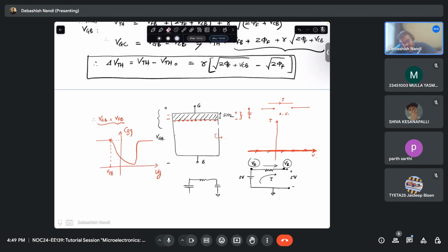Let's say you have some kind of source here. This is R, this is C. You apply a pulse, a current will flow, and at infinite time, what will happen? This is the step you are applying. How will the voltage across the capacitor be? Let's say VO will be something like this. So 5 volt will appear after some time, let's say 10 tau, where tau is equal to RC. It may not be exactly 5 volt, but 4.9 and much beyond that.